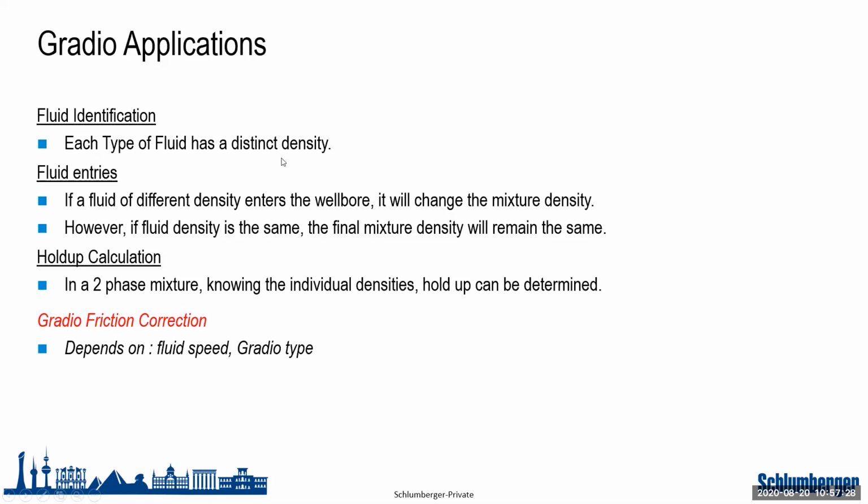So now, what are the Gradiomanometer applications? You want to understand the density of the fluid in the wellbore, okay? You can identify entry of a light phase into a heavy phase, or the opposite, entry of a heavy phase into a light phase. Why? Because you will see a change in the wellbore fluid density, okay? And at the end, the density of the mixture you can use to derive hold-up, okay?